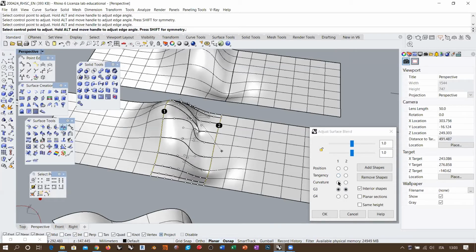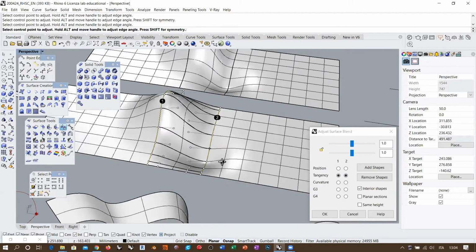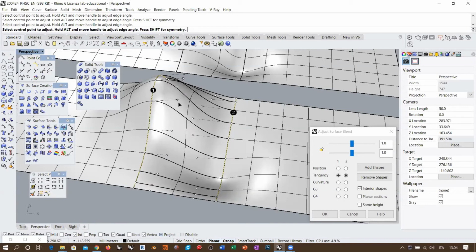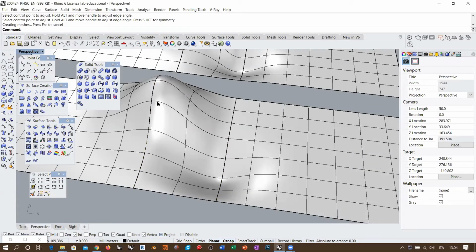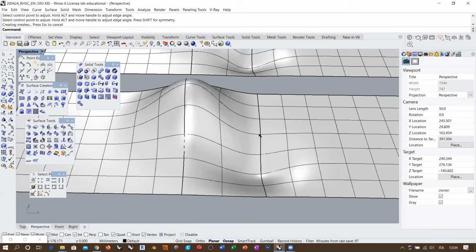So the blend surface and the blend curve, they don't allow controlling the degree, because they only allow controlling the geometric property, not the topological property, okay? So yes, you can still have this, but you must perform something like this. Well, let's do it at once, okay? So tomorrow we will start with another thing. You want a degree 3 surface, and then you take tangency in order to create the first version of this connection, okay? Of course, it doesn't have curvature continuity, but it is degree 3, okay? And it approximates the connection with some higher level of continuity.